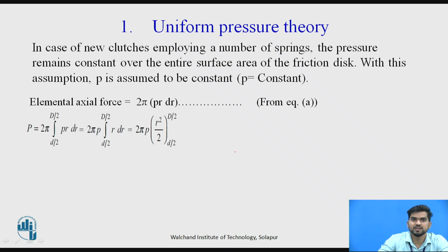Then for getting the total force, capital P, we have to integrate. Just I will draw the figure here. These are the two rings. This is the center. In between, this is the friction lining. I have to consider this area for getting the total amount of force.